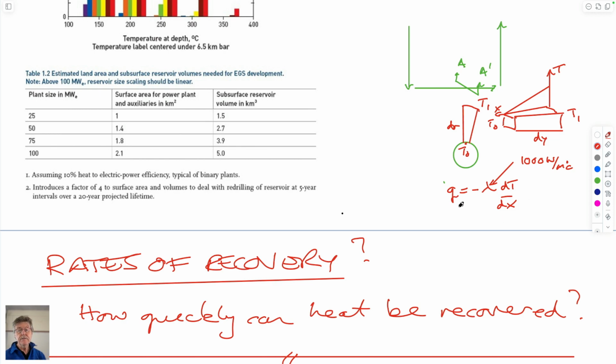And because it's a very small number for this thermal conductivity compared to driving heat flow across, where basically advective flux would say that you're taking this block of rock and you're physically transporting it to this end in a given amount of time. That's what physically convection is. You're not really moving the rock, but you're transferring the heat in the rock into water, and then that water is moving into the wellbore. We're not doing that in this case. We're driving it only by conduction. And you can do the calculations, and it ends up being a very small number compared to what you'd expect.